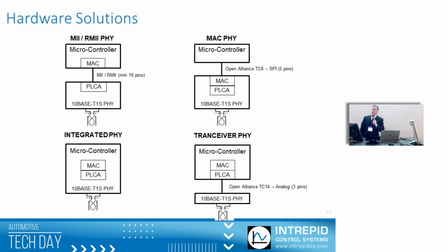before that, one of the other limitations with Ethernet compared to CAN-FD and CAN is that Ethernet up until 10BASE-T1S requires an MII interface. There are many different MII standards out there, but the one with the minimum number of pins is 10 pins. Ten pins for silicon on a PHY is very expensive from a real estate standpoint on a PCB. And a CAN transceiver, you can get with like 3, 4, or 5 pins, including power. So Ethernet in that way has not been competitive with CAN because of just the pin count and real estate size of the chip.